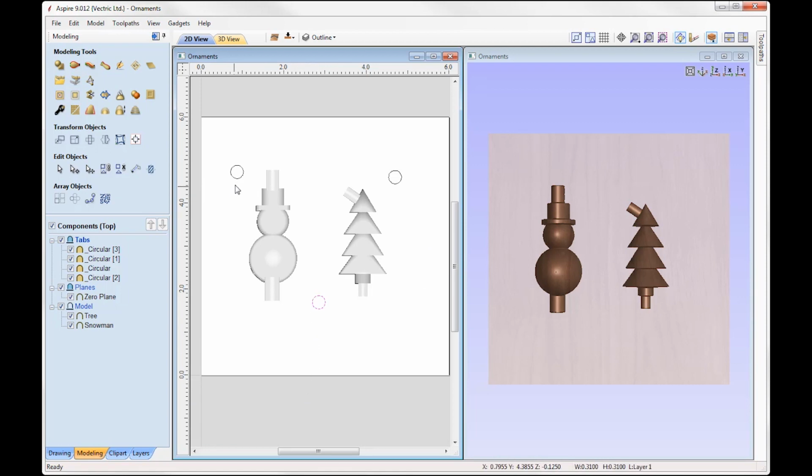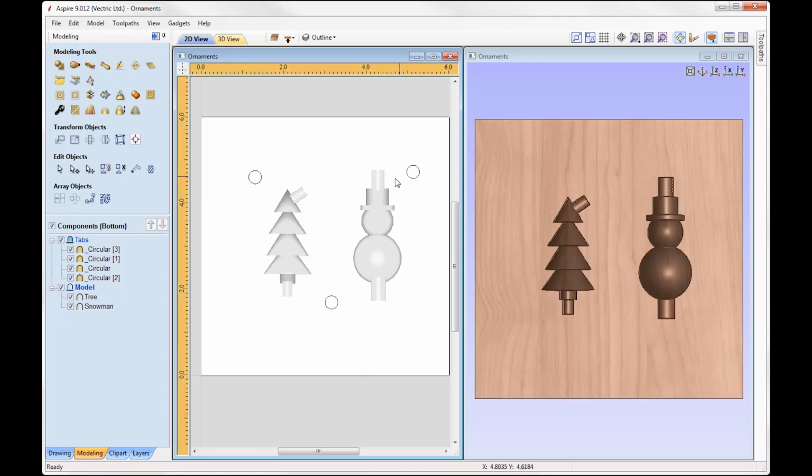These circles represent the holes for our dowel pins, which we're going to use to locate our X and Y positions when we come to flip our material over to cut the bottom side. Simple, we just select everything and copied it over to the other side like so. So we've got the exact same on the bottom side. The only thing that I haven't copied over is the 0 plane. That's not needed on the bottom side. We only really need that on one side.